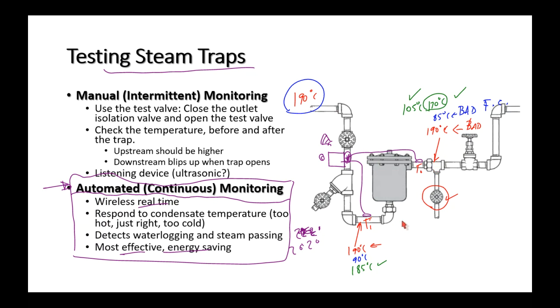Or maybe what I could do is use crayons. So we have these crayons that have a known melting temperature, and so I can apply the crayon there and it melts over there, and I apply the crayon over there and it doesn't melt, and then I know that I've got a delta T, a delta temperature.